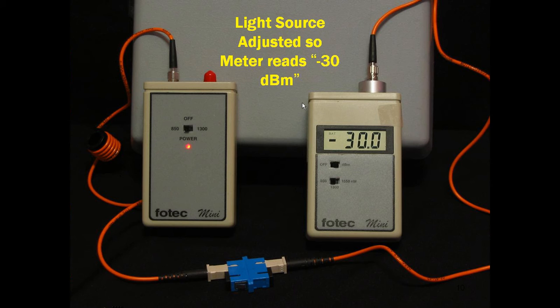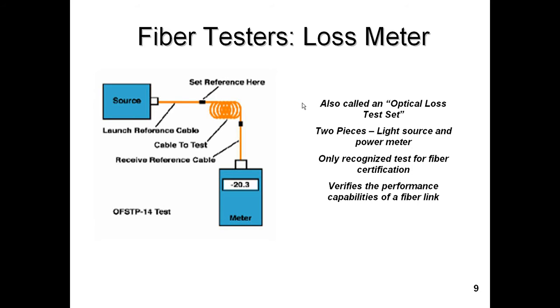Nowadays, on a modern meter set, there would be a 0 button on the power meter on the right-hand side. And once you have hooked up your test leads to make sure they're good, you would press the 0 button, and the reading on the right-hand side would be 0 dB. Now you're going to read decibels of loss. So when you hook it up, as you see in this drawing here, you could see how many dB of loss is there in your test cable, and it's going to show up on your power meter. And this is standardized.